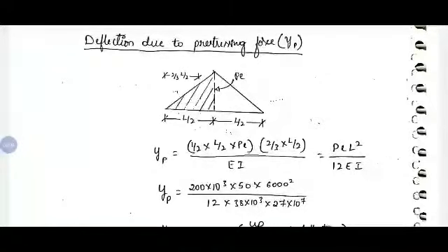Since we have a triangular shape profile, the bending moment diagram with respect to prestressing force will also be triangular with a maximum height of P into e.